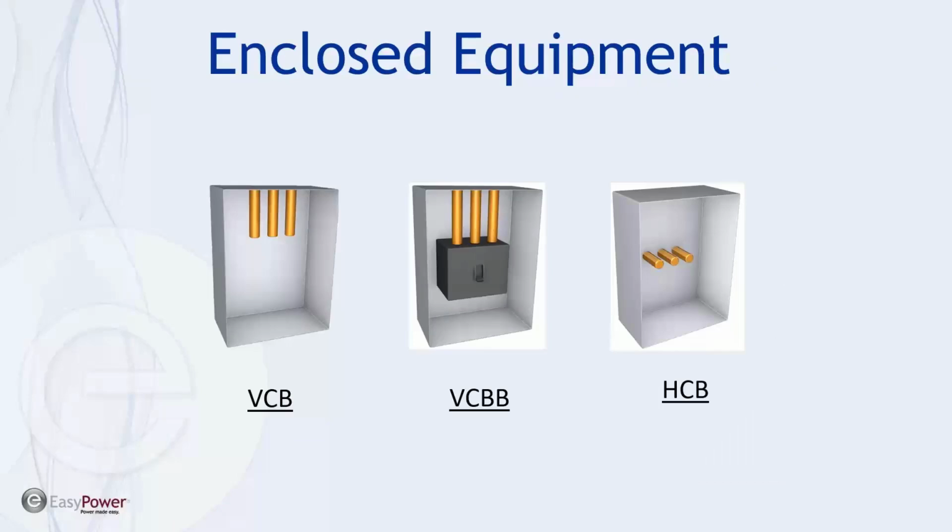Just a real quick point. Again, this is something that's been covered ad nauseum, but this is the example of vertical in a closed box, vertical terminated in a barrier in a closed box, and horizontal in a closed box. And the issue is where the plasma blooms or spreads out. Tests have shown that if an arc forms on this bus work, it travels to the butt end of the conductors themselves, and then blooms down.